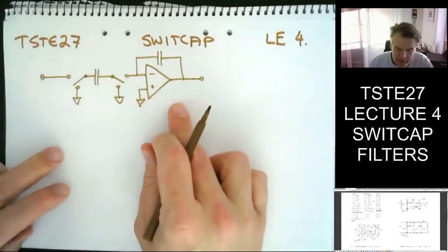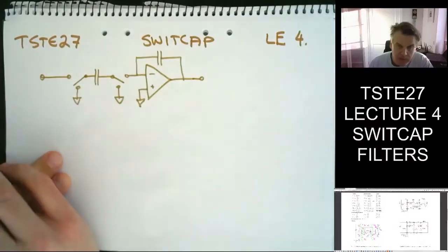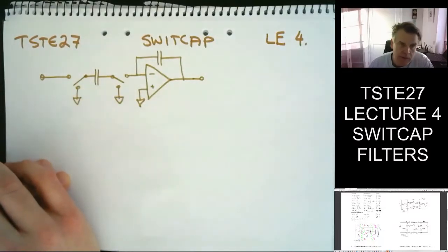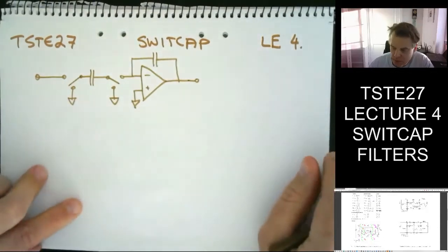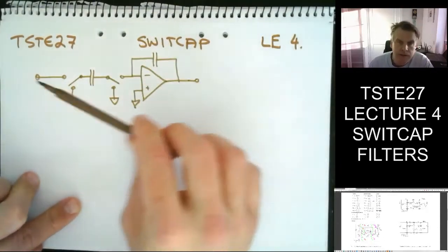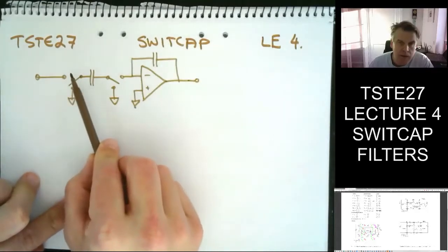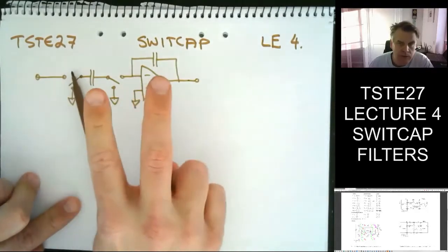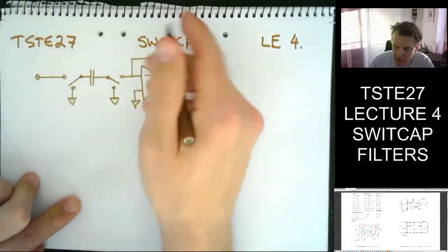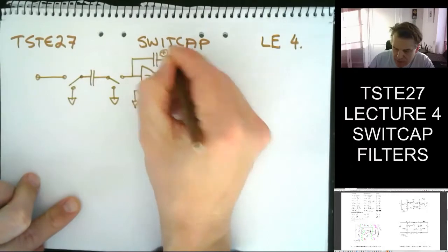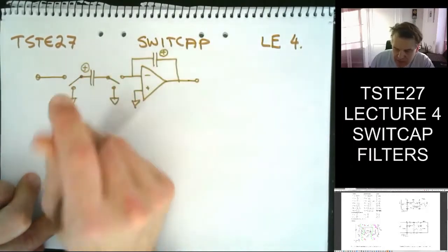If we did the analysis on this one, we did the charge redistribution analysis, and we spent quite some time last time, and I suggest that you practice a bit, but essentially it's quite simple. We have two phases, so we have to note down the states of those two phases, the total charge on each of these caps. We introduced some reference directions like this.